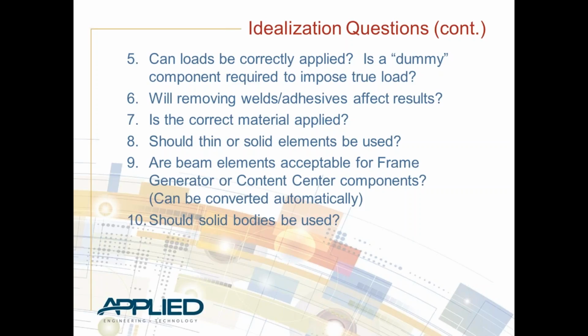Obviously, if there are fillets and rounds and stuff like that, it's kind of the same thing. Sometimes if you have a sharp corner, that's where your stress might be. So you might need to leave that round in to make sure the stress in the actual analysis is more realistic and more lifelike than if you take some of that stuff out. So some things to think about there.